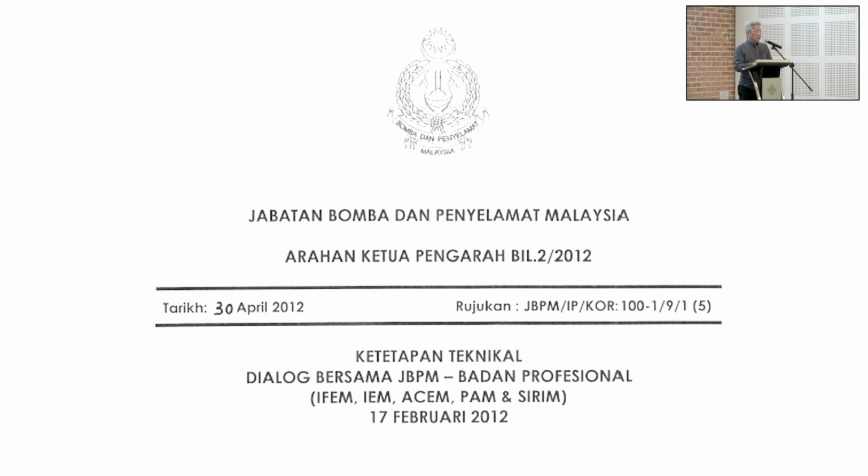So very creative architects, what they've done is indicate all these compartment walls to limit the building. So they have this huge multi-storey building with huge floor plates, and they put in these drywall partitions. Fire rated, because Knauf gave us a certificate, tested to BS 476 Part 22, 2-hour fire rating or 4-hour fire rating. So they did that, so that they complied with the compartment limits. One giant warehouse, and they have all these partitions.